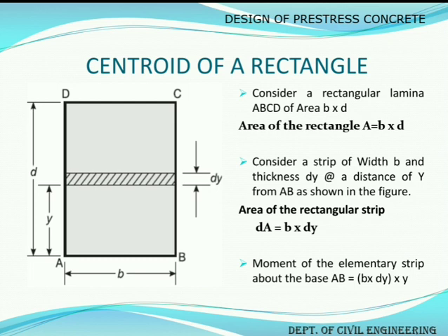So remember this, whatever is the axis under consideration, we will need to find the perpendicular distance as the centroidal distance. So in this case AB we are taking as a reference axis, about which all the moment needs to be calculated. Hence, our derivation will end when we obtain y bar.